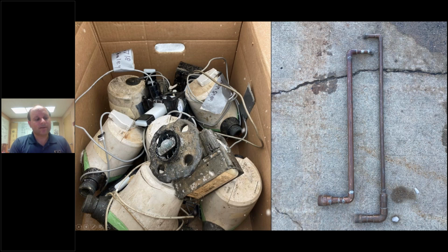Another issue that the city of Lafayette did, which was great, which we recommend, is once you valve off these buildings, pull the water meter. We don't want people going in and turning their water back on because they could back siphon contamination to the water system. In East Boulder County Water District, the small water system did see that happen. So the city of Lafayette started pulling its water meters for all these destroyed properties, and they developed a system to do sampling.